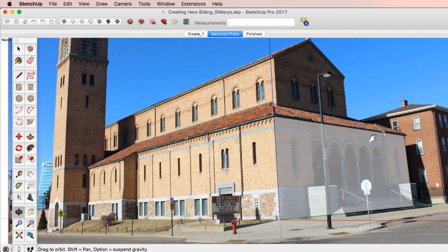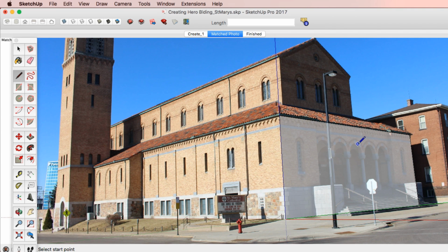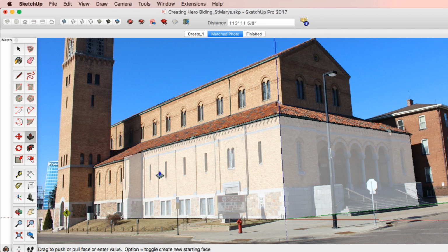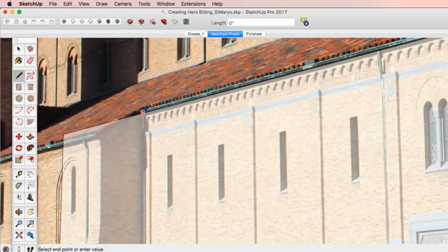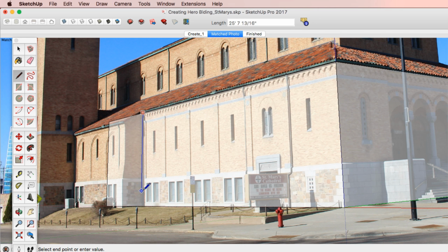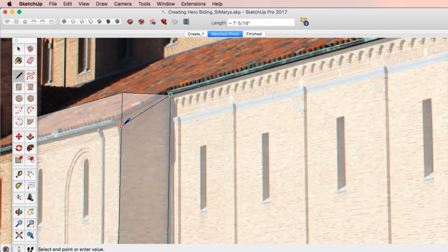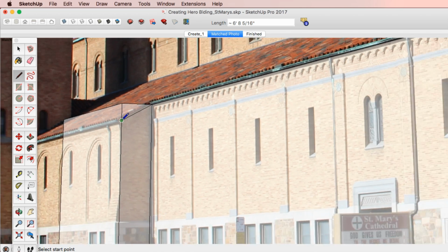You see here I'm going to be doing just the front facade part, the lower half, to create a surface, and then we'll push this back using the push-pull tool again. Okay, and maybe I want to, you notice how the side facade there actually juts out a little bit, so I'll create the seam there, and I'll push-pull this back out to start that. Okay. You can use the photograph to actually figure out the pitch of the roof.